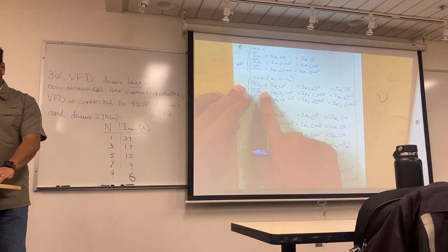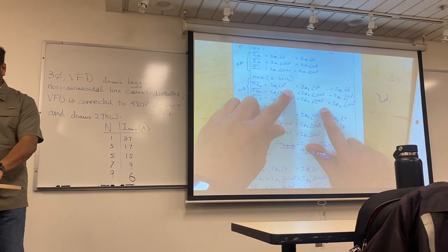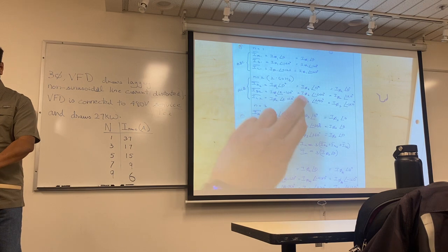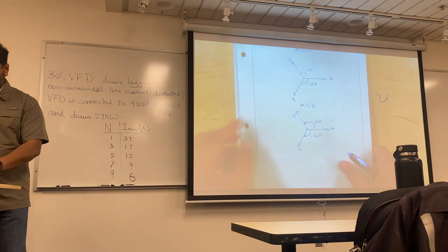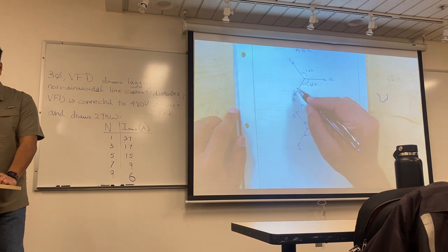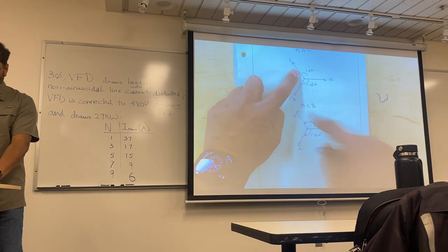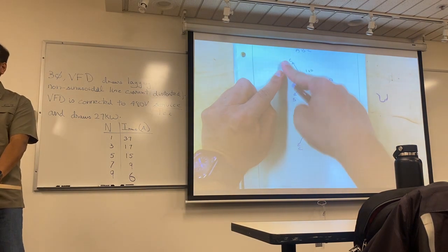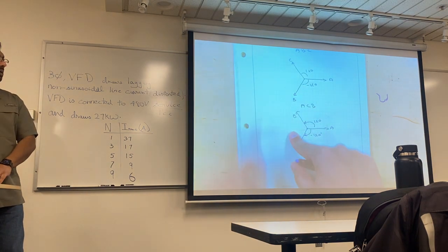When you go with your IA2 and you get your 0, negative 240 and 240, keep in mind this, let's just look at this IB2, which is with negative 240. So this is 0. If I go this direction, this is minus 120. And if I go one more negative 120, I end up here. So what's happening is my B got swapped with C, and my C got swapped with B. Do you guys get it?